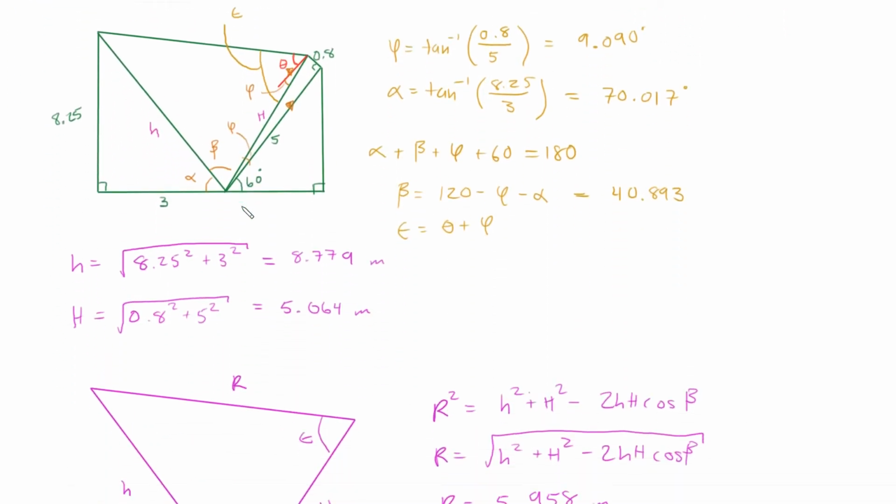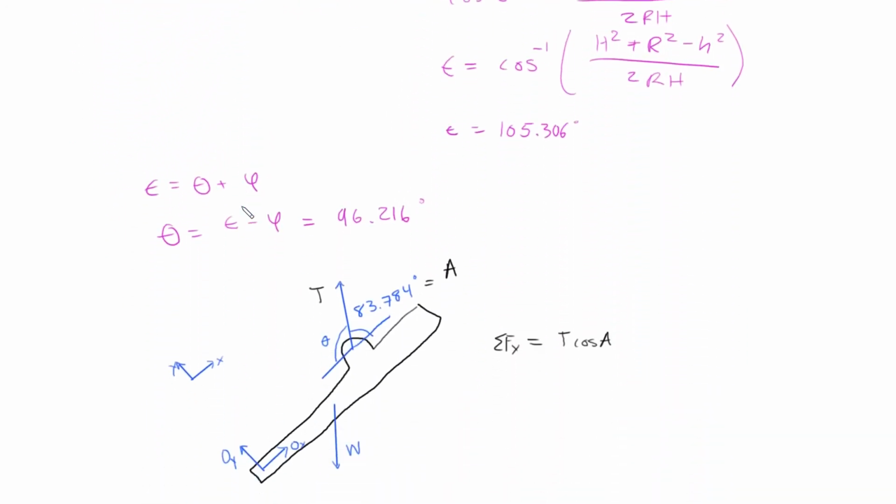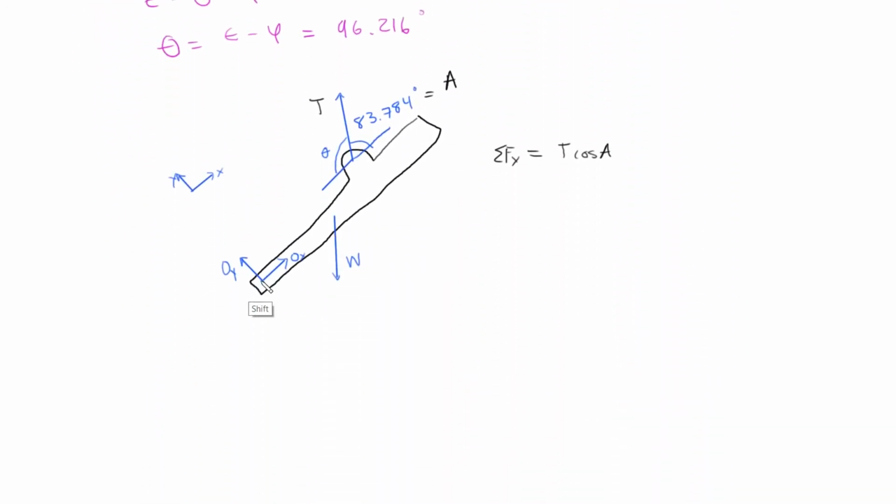So we're going to define that right now. 60 degrees from the horizontal. So this is going to be 60 degrees. And by that notation, this line is perpendicular to the beam, or it points in the y direction. This angle right here is going to be 60 degrees. So now we could define W, so it'll be minus W sine of 60.